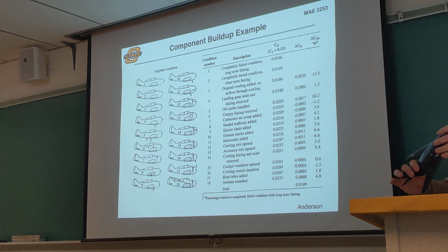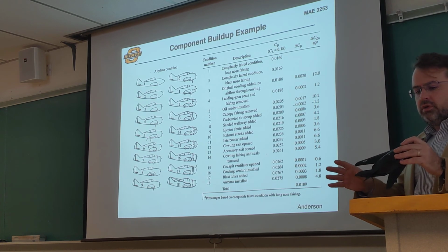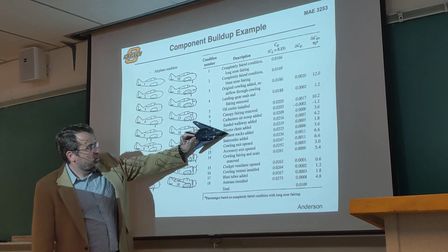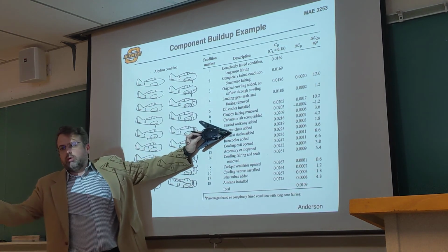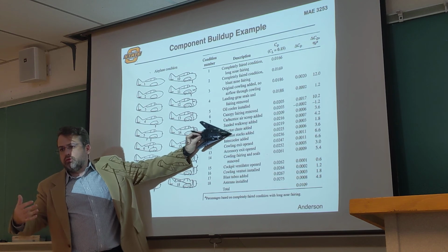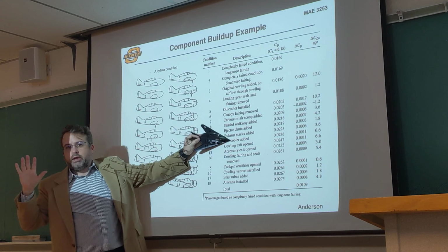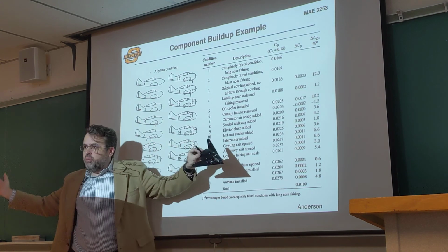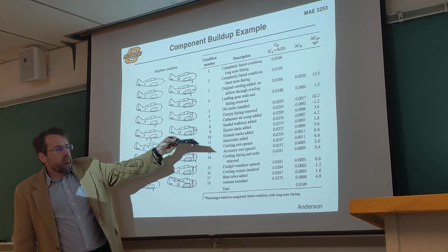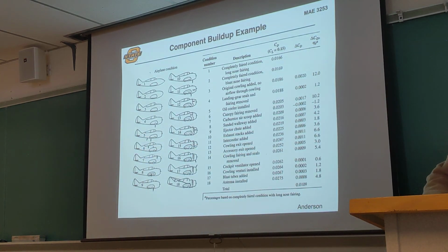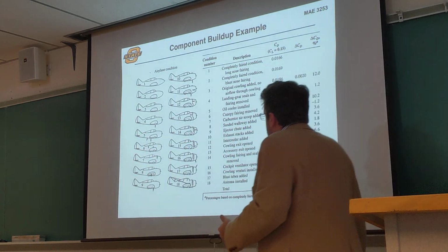Because when it's running that solution, in a typical CFD solution, your aircraft is going to look like this, and then your entire domain that you're solving for is going to be about the size of the entire chalkboard. So it's calculating flow way out here, and flow way back here, and flow off to the sides and up and down, and that whole three-dimensional geometry. So you want to minimize all your complexities in your geometry as much as possible.